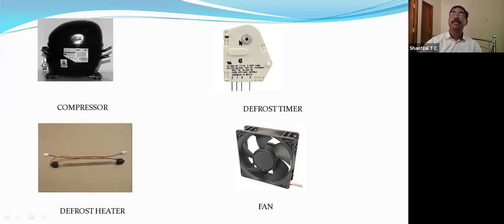After 5 minutes, here cam will be there. After 5 minutes, automatically this heater will be off and compressor and fan will be on. Regularly, at a particular interval, this defrost timer regularly defrosting the system. This is known as time shutdown defrosting method.